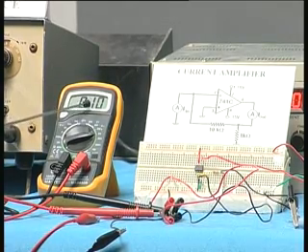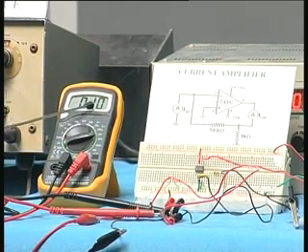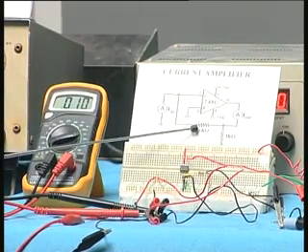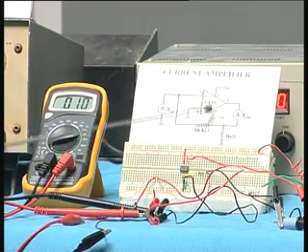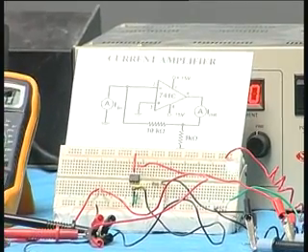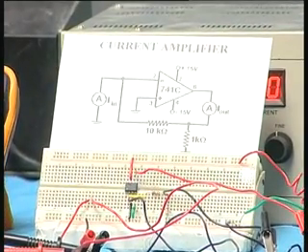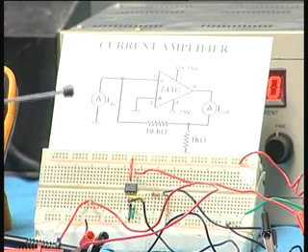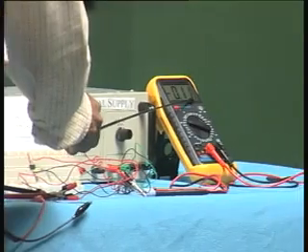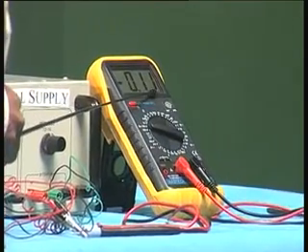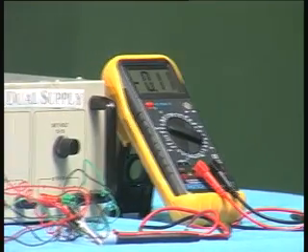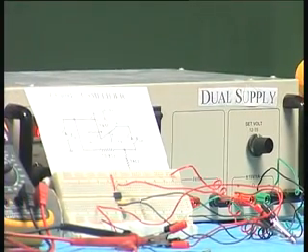So 0.010 milliampere is 10 microampere basically, and because the gain is 11, 1 plus R2 by R1, where R2 is 10K and R1 is 1K, as you can see in the circuit on the top. So 1 plus R2 by R1 is 11. 11 times 10 microampere is 110 microamperes, and in milliamperes it should read 0.11 milliampere, and you can see it reads 0.11 milliampere. There is a decimal point here. So it is exactly multiplied by 11 with reference to the input current.